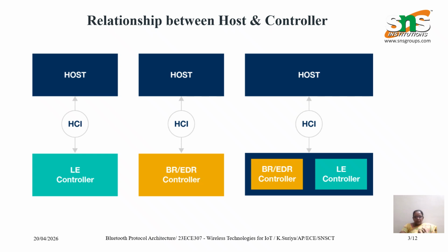This is especially relevant because in complex systems like PCs and smartphones, the host is generally implemented as part of an operating system, while the controller is in the firmware of a separate hardware peripheral over which the OS does not have any direct control. So a user interacting only with the host will generally not have control or knowledge of what happens in the layers implemented in the controller, since it is an isolated element, usually with proprietary firmware from the manufacturer.